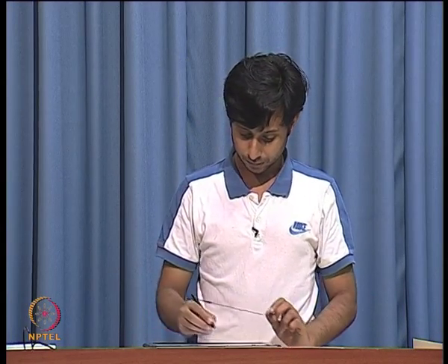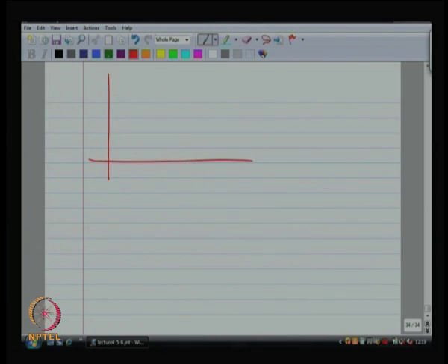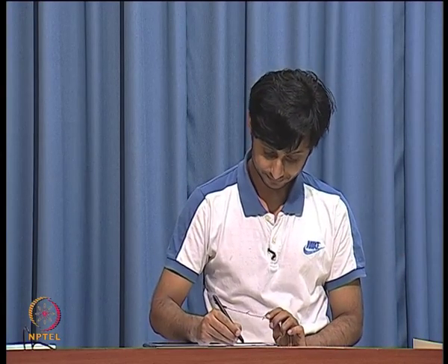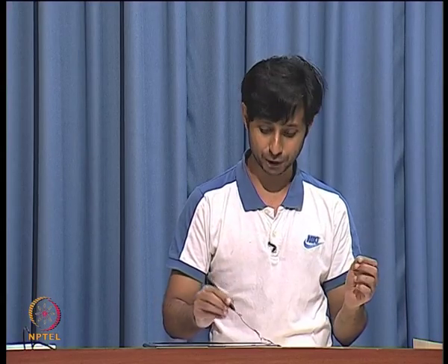So, you have got a little bit of freedom over here. The total q can be larger than q 1 and q 2. So, suppose with an L match, this is what you were getting. This is my frequency axis, this is Z n. Okay. This is what you were getting with an L match. With a pi match, you can make the Q sharper. You can't make it broader, unfortunately.